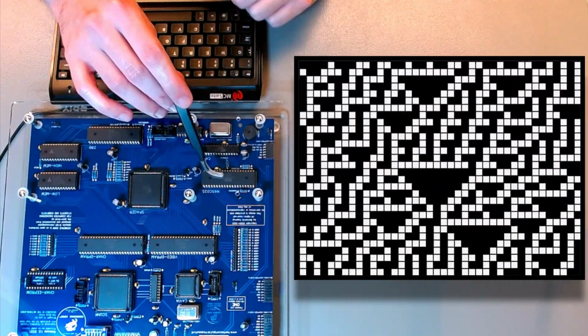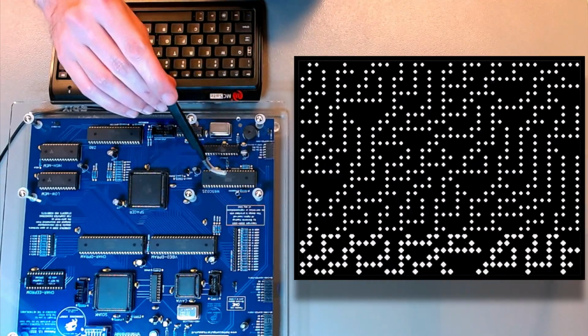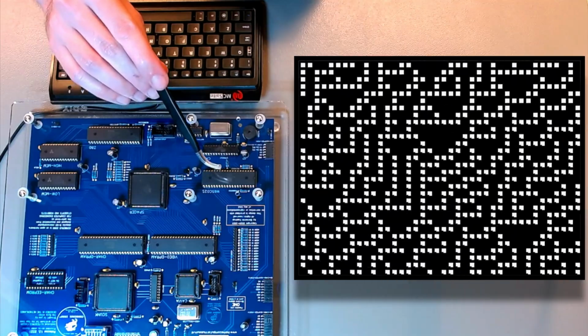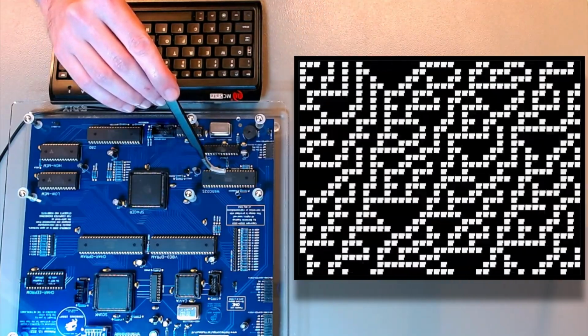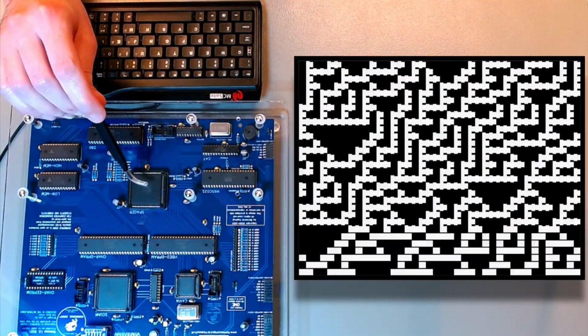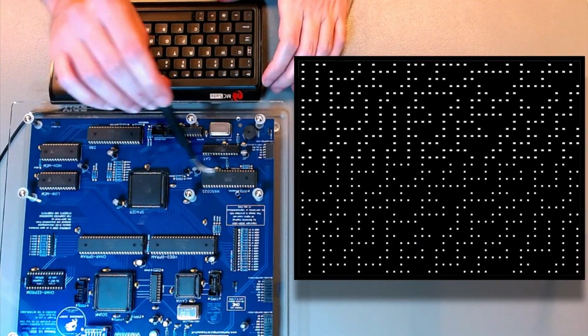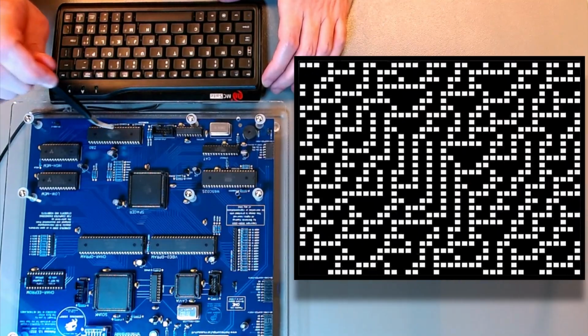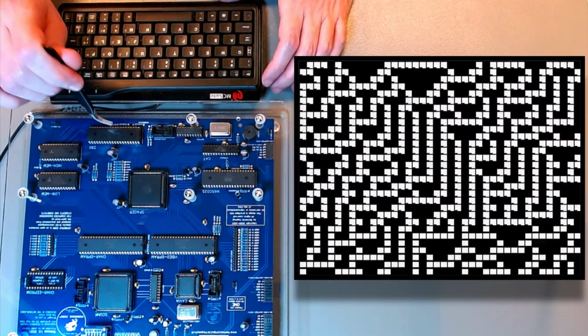It's not really a complete CPU. A lot of the timing protocol that has to be implemented before we can pause the 6502 is actually implemented in the CPLD here, which communicates to the 6502 via a slow PCB. In the Z80, this is all done internally in the die of the Z80.